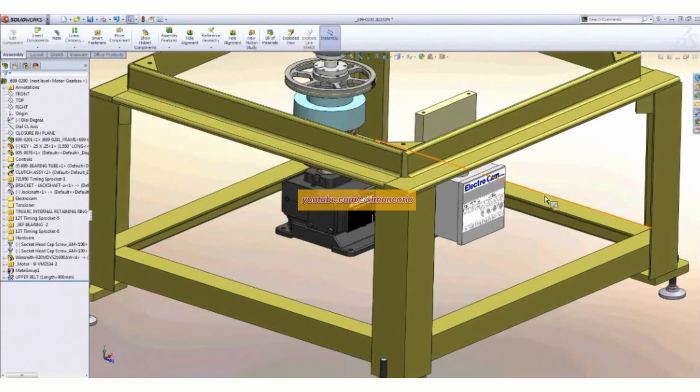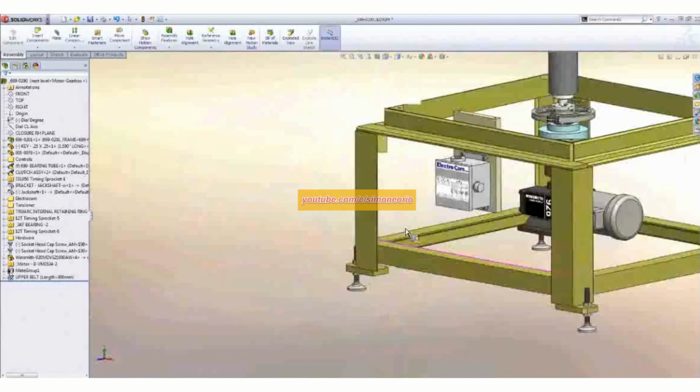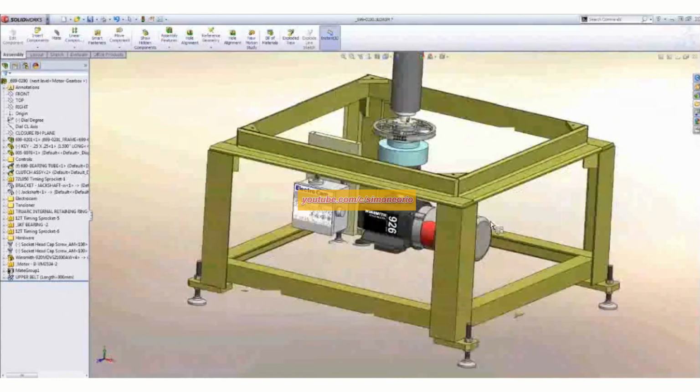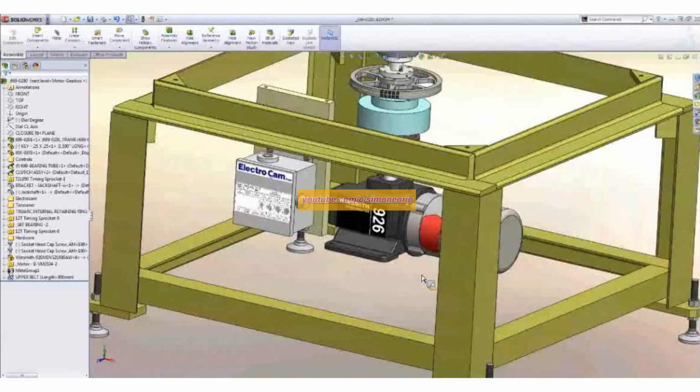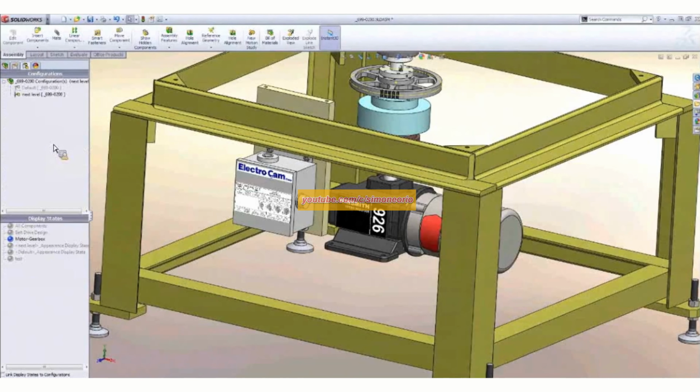Is there another question? Yeah, with display states, you said that they can be used without configurations. You can just make things show up. When do you link display states? That option it says link. Right, there is an option at the bottom to link display states to configuration. So basically, the only difference is this: if I don't have this option checked on, I can have 20 different configurations, but all of the display states I've created are available in all of those configurations.